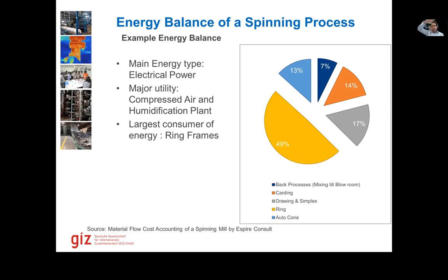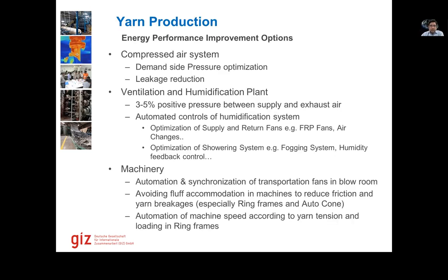From the top, we provide more air, and from the bottom, we do an exhaust. The air from the top presses the suspended particles downwards towards the exhaust, which is from the bottom, from the floor. Then the whole air carrying the fluff goes through the exhaust and into the filters, so that all this fluff and dust is collected inside the filters, and the clean air is then exhausted.